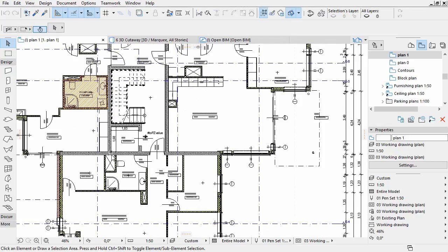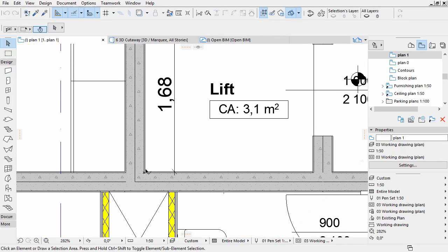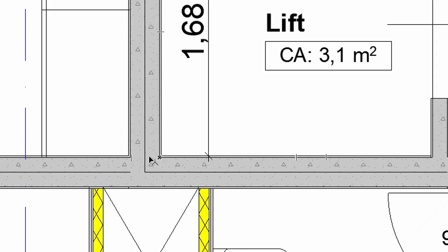Define a typical point of the building as the project origin. In the future, share this point with the disciplines working in other software. During the design process, they should take care to place elements with respect to this project origin. For instance, this point can be a wall floor joint, so we just have to define the offset of the floor, marking the joint.